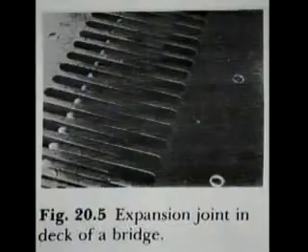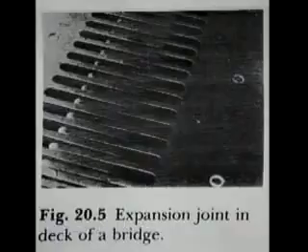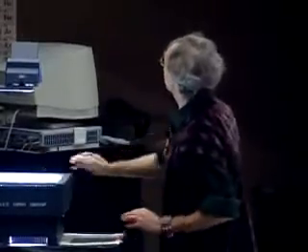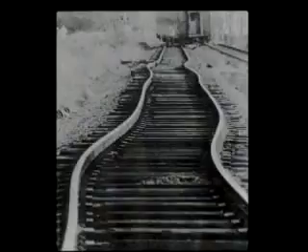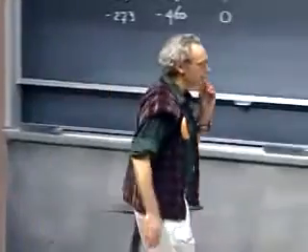There is a bizarre picture whereby the claim is made that this railroad became so warped because of an extremely hot day. I trust it, although it's hard to believe that it could be so bad. It must have been extraordinarily hot. As I mentioned, if a rail cannot expand, then all it can do is bulge in this way or this way, whichever way is easiest for it. And apparently here, the easiest way is to go sideways. So you see a remarkable destruction, actually, due to an unexpectedly high temperature.